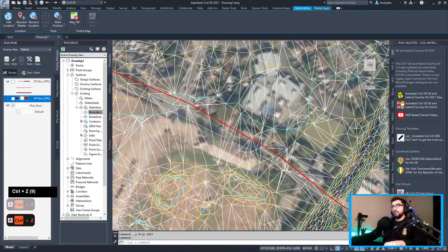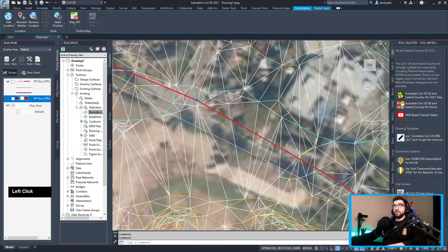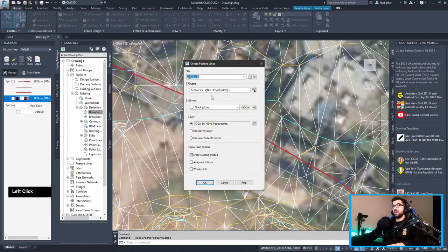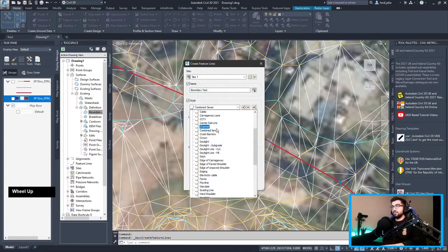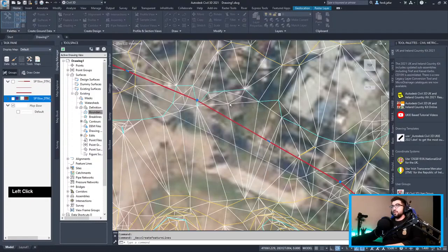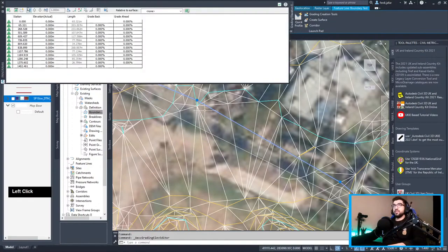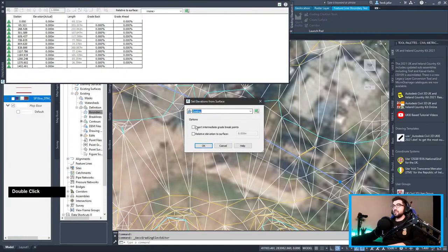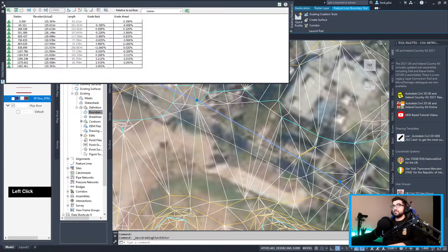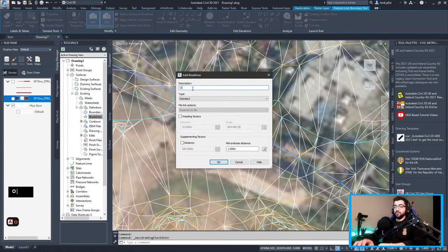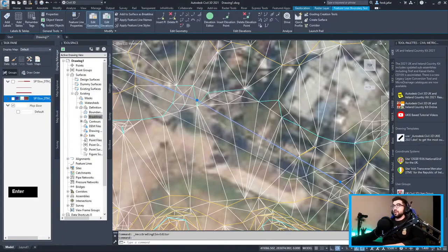Watch this out. So let's say we didn't do this with the boundary line, right? And we offset it. So what I would do is select this polyline, go to feature lines, create feature lines from objects, right? And let's name it boundary test. And grading, let's give it a basic one. And okay, so now it became a feature line. In the elevation editor, go to elevation from surface, and then select the existing and hit enter, and then exit. Now what I'm gonna do is add this breakline into my existing, so offset boundary, okay.